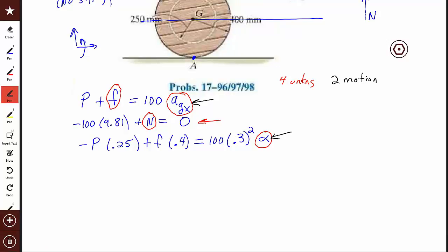I'm going to write the acceleration equation between A and G. Acceleration of G, it's a vector, equals the acceleration of A, it's a vector, plus alpha of the body they're on together, which is the spool, and I've already assumed that it was counterclockwise. You see, because I put it in right here with a plus, saying that I thought it was counter.